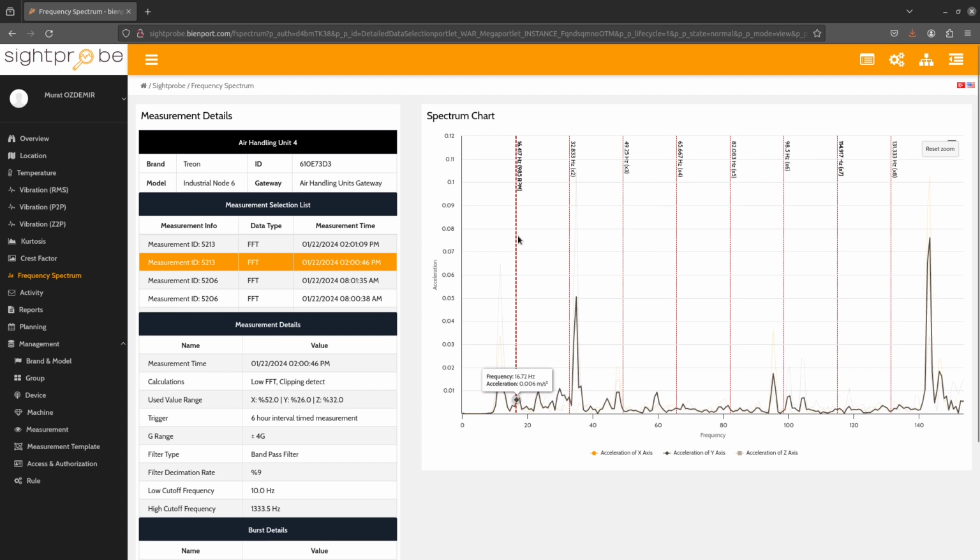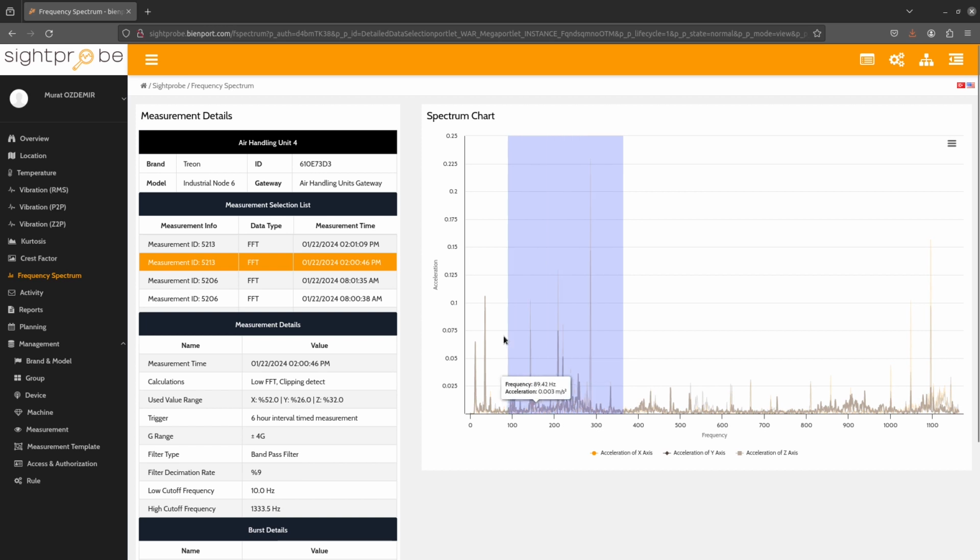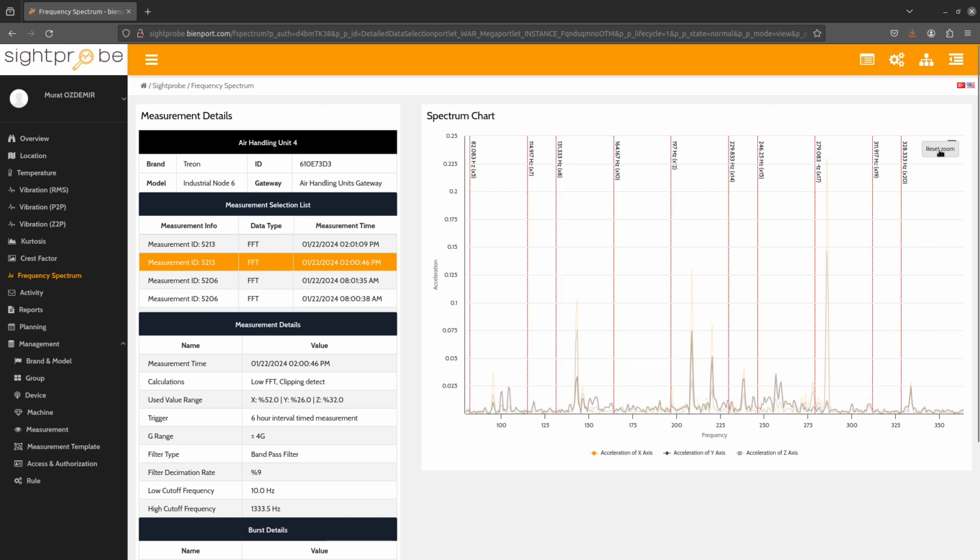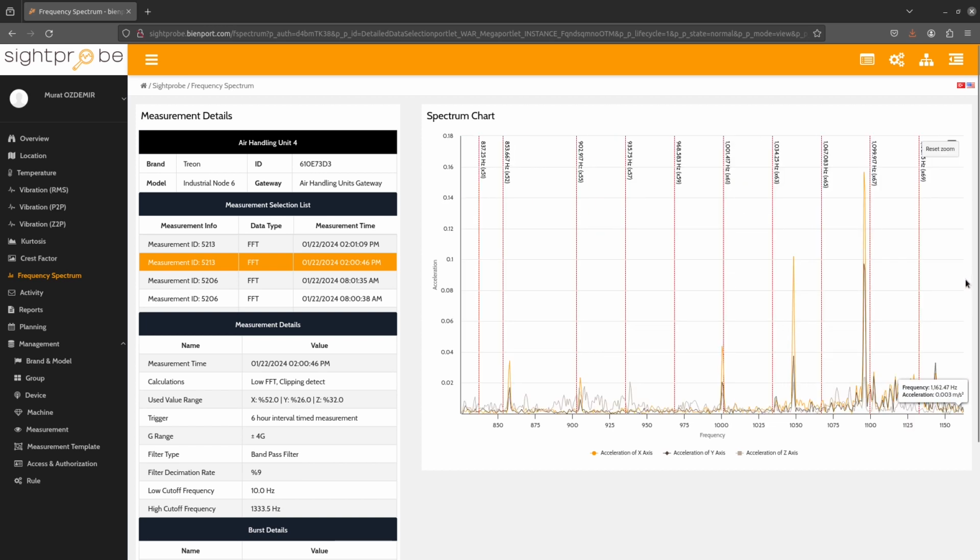The other harmonics are shown with a thinner line and smaller font, along with the number of times the engine speed. These harmonics provide very useful information for detecting mechanical imbalances, misalignments, gear and bearing failures, detecting electrical problems and monitoring motor load conditions.